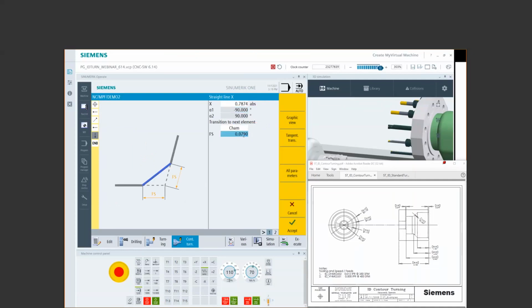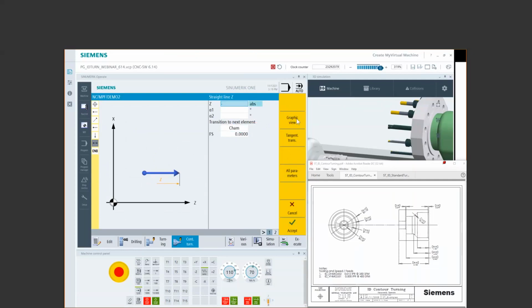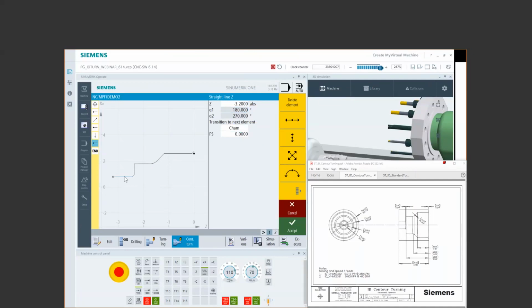Since I drilled it with a 3/4 drill, I'm going to want to send that boring bar through there. So I'm going to give it a Z move and probably go to the 3 point, maybe a little bit more, 3.2. Remember the stock's 3.150. Now, if I want this tool to go straight through here and I don't want it to take any roughing cuts, then don't do a pull off at the end. The system will allow the tool to go beyond this point by the radius of the cutter, so be careful if there's a blind hole. If that would be an issue, then you would want to pull a retract in X. But if that's okay, like in my case, I'm just going into the spindle bore a little bit, I would not pull a retract out.